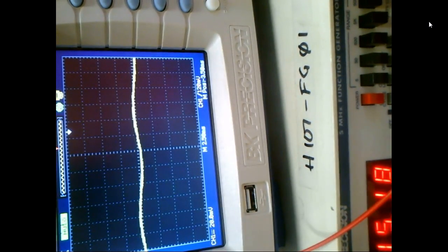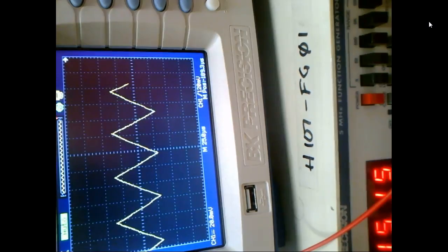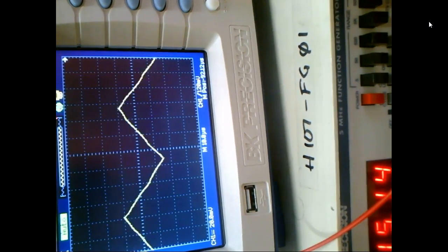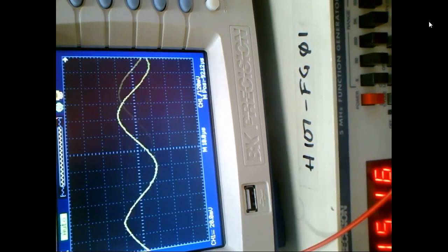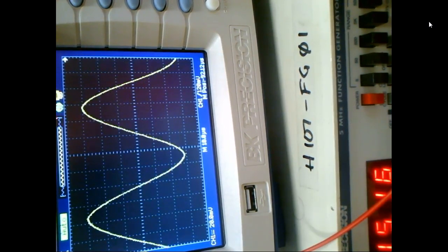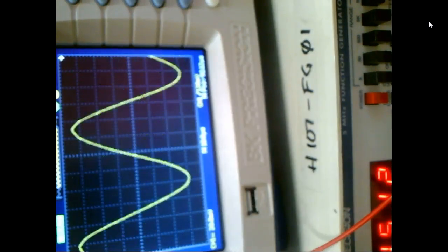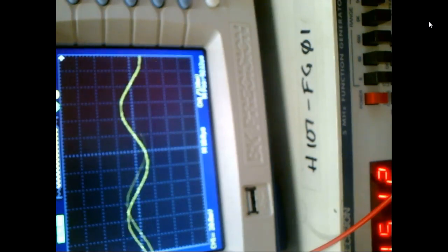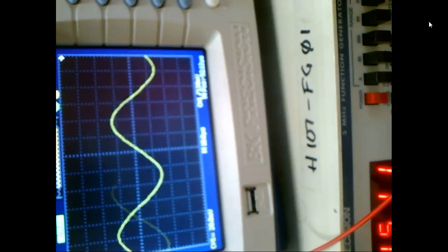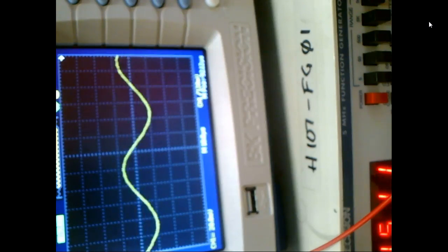There's nothing common between these. We're actually creating a capacitor, and we're passing the actual frequency. Of course, we can't get away from DC. Let me put this on it. So this is what we're passing. We're passing the AC through there. So the closer I can get them together, the higher the AC is coupled between these two. Y'all see this, right? Which is pretty neat. And then I come over here and do this. So here I'm adjusting the distance between the plates. Here I'm adjusting the size of the plates. So this is how we can make them variable.